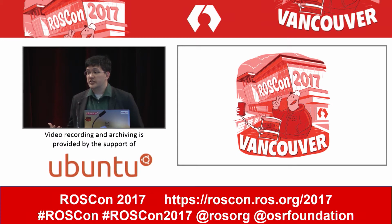I don't have a solution for how to actually handle slippage in the wheels. I know it's something that we as a team are working on, being able to integrate an updated kinematic model into the local planner. So by making that section a plugin, hopefully you could be able to dynamically fix it. So is there a plugin interface for that at the moment? For the plugin for the trajectory generator? For the forward kinematics of the rollouts? Yeah. Yep.